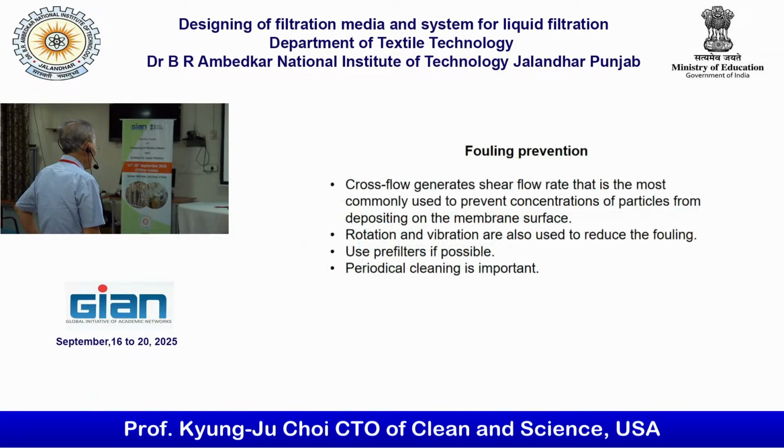Fouling is a big issue actually. That's why they use the cross flow, generally shear flow. Rotation, vibration are also used to reduce fouling. Certainly, pre-filter is really important. Periodical cleaning is important as well.